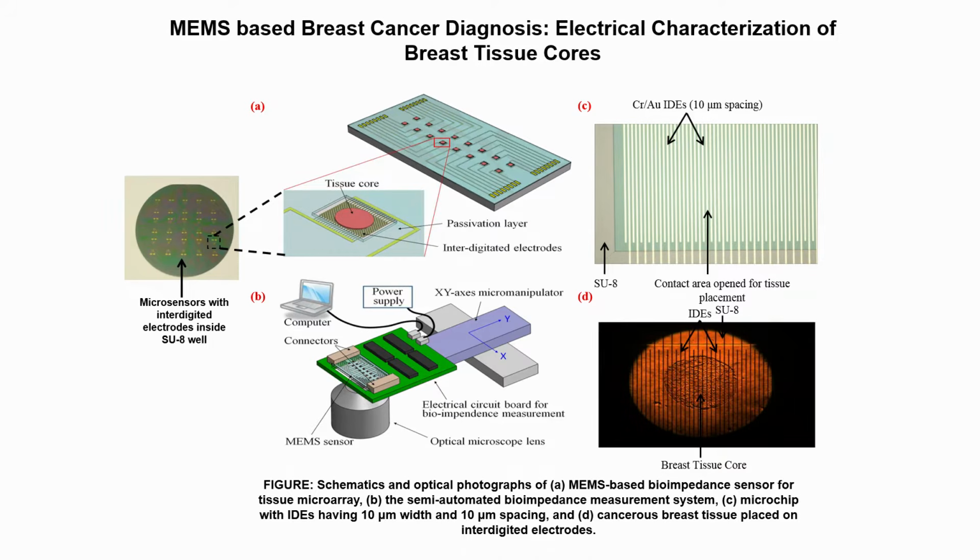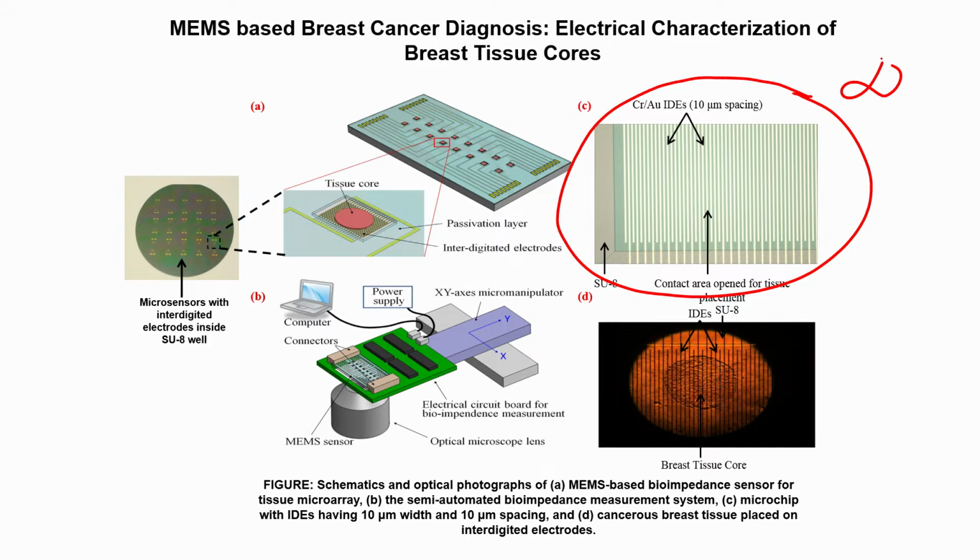these are the interdigitated electrodes here, okay, and what will be the impedance of this? The impedance of this would be infinite or extremely high. Why? Because there is nothing on these interdigital electrodes, and there are only metal lines not connecting with each other, right.